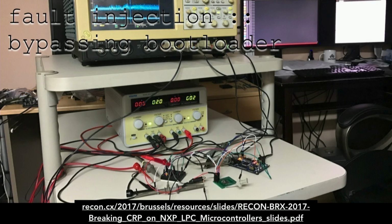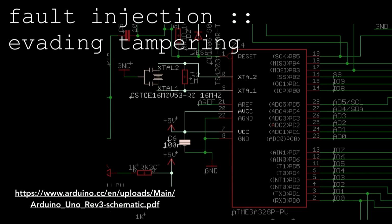This is an example from Chris Gerlinsky's setup. Several years ago, he demonstrated bypassing the NXP LPC bootloader, which is used in a ton of chips. It's used in various locks, all sorts of interesting things. And essentially by removing the bypass capacitors and performing a voltage glitch, you can then bypass the boot protection that actually protects the flash if you're trying to, say, release a product and store some keys, store some secrets, store some firmware that might have other faults, might have vulnerabilities in it. You can bypass all of that with a simple voltage glitch.